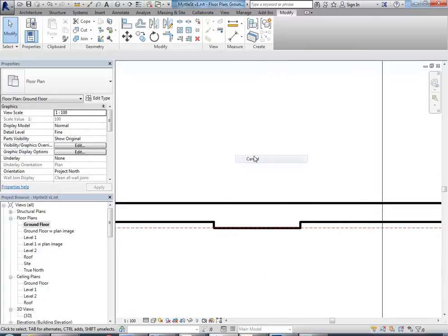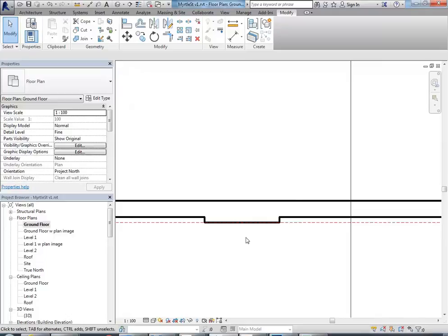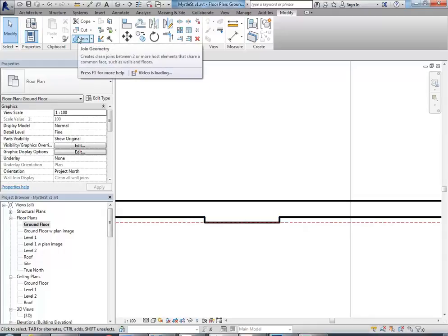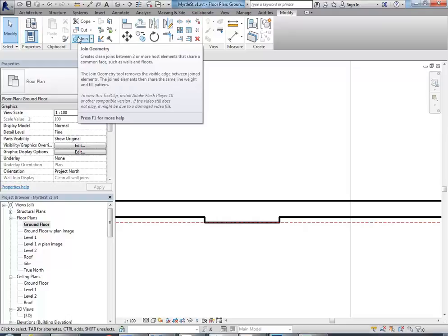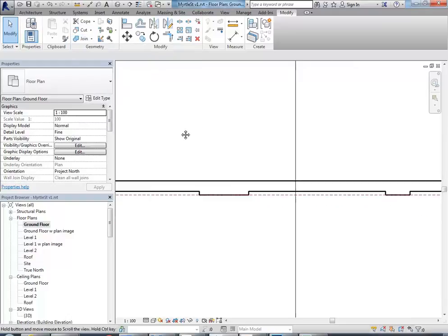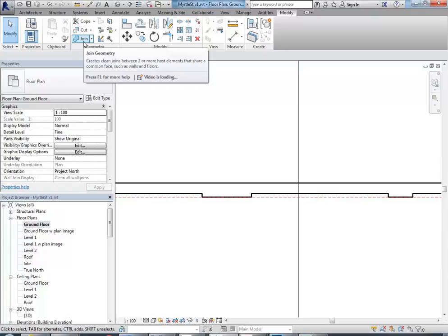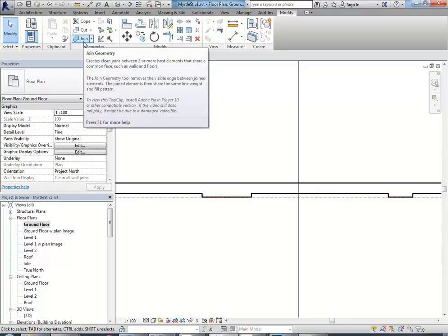It's really common with interiors to need walls that change thickness or overlap in different ways, but still need to read as one block in plan. So make sure you know about that join tool. It's really, really useful. Join geometry. Have you used that with things that you've modelled, like solids and extrusions? Oh, okay. Well, if you haven't, it's really useful with those. Extremely useful.